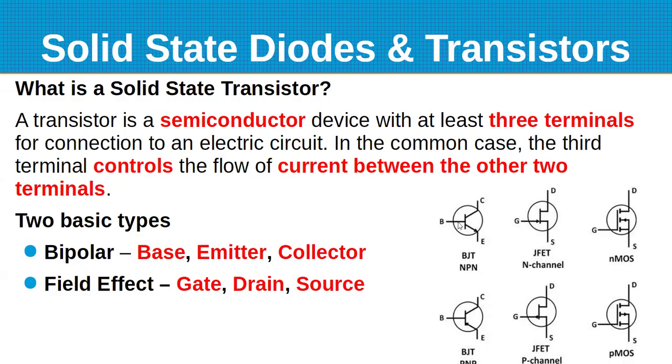So by adding that third piece, we now have a device where we can control the current flow between the collector and emitter. Because if I think of this diode, the PN junction, where I apply a voltage to the base or the P material, I get current flow if it's more than 0.7 volts, if this is a silicon device. When that happens, and I'm not going to go into how, it causes additional current to flow through this other piece of N material out through the collector at a multiplier of the current that's going through the base emitter. And we call that gain. Sometimes they label it something like HFE or transistor gain.